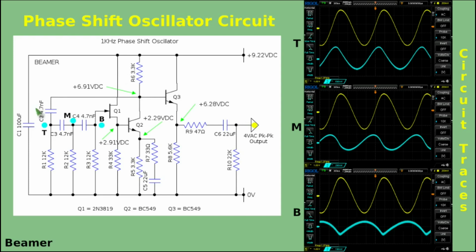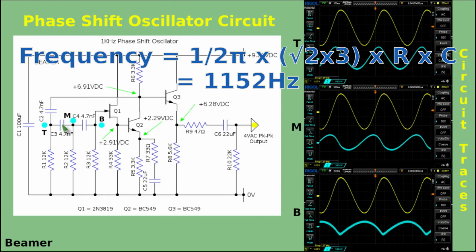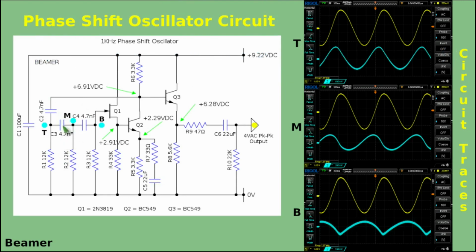The frequency of oscillation can be altered relatively easily by adjusting these components of the phase shift network, bearing in mind that they have to be the same, as I mentioned earlier. You can increase these capacitors, you can reduce these capacitors, you can increase these resistors, you can reduce these resistors. The network itself can become quite a low impedance, so the relatively higher impedance here of maybe 1,000 ohms or slightly more, a couple of thousand ohms, imposes a limitation as to how low an impedance this network can be set. So you're better off with higher value resistors, smaller value capacitors.